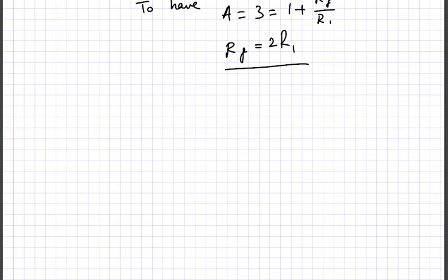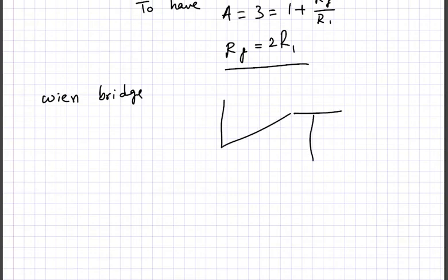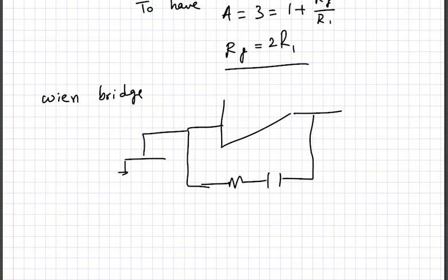And then the Wien bridge name is basically... Sorry, I always get confused with this. WIEN, Wien bridge is the feedback path at the bottom that consists of one capacitor and a resistor in series, and one resistor and a capacitor connected to the ground. So RC, this is known as the Wien bridge.